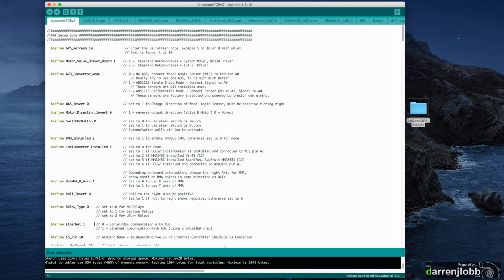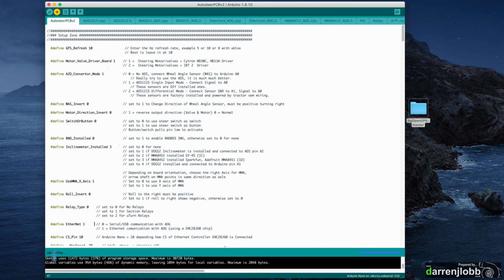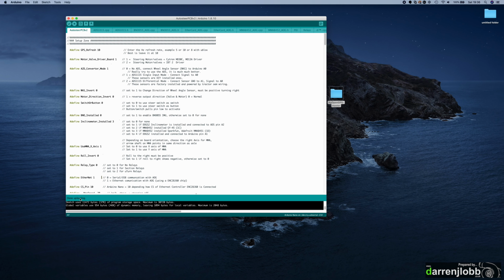So once you're happy with everything, you can come up to the sketch menu and hit upload. You can see in the bottom it's compiling and uploading. So now it's basically uploading this onto the Nano. And the minute that it says done uploading, it should now be uploaded and running.